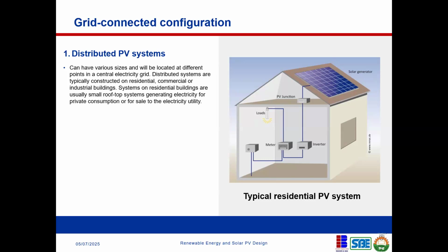I've explained how your home can have a solar system that is connected to the grid. I told her that it is called net metering, where you have a meter that reads in both directions. It can send from your solar PV system to the grid, and it can also collect from the grid back to your home. So it's a two-way metering system, and it's called net metering. It's available in some countries. I know Kenya recently drafted their own regulation on net metering. It's available in India. It's already very common in Germany and some other developed countries.